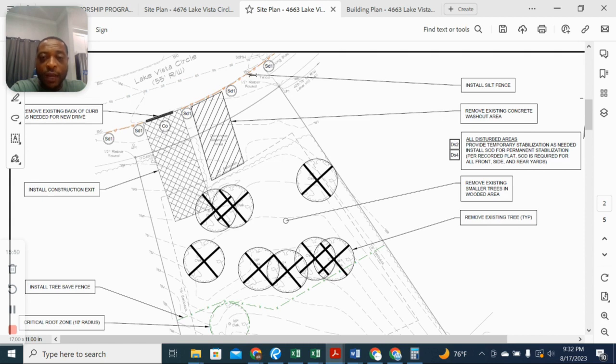We're going to discuss that. What is a silt fence? The silt fence is that black fabric that you see when you go to construction sites. And I'm going to share some video with you, and you'll see they have some black material surrounding the property. Usually it's about maybe 3 feet high. It is to prevent silt, dirt, from leaving your site and washing out onto the street.